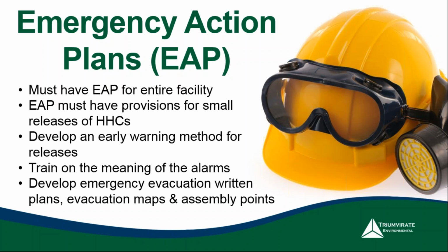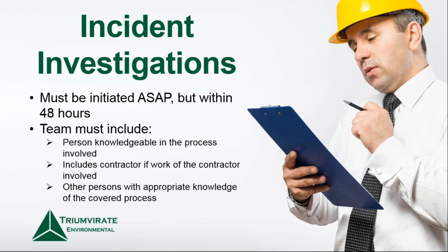Most people take it too nonchalantly and don't take the real importance of getting out quickly. You really want to stress to them that if we had an alarm in one of these processes involving the high hazard chemicals, they really want to get out and get out quickly. So you can't take for granted that it may be just a drill. It's very, very important that you instruct your employees on that front.